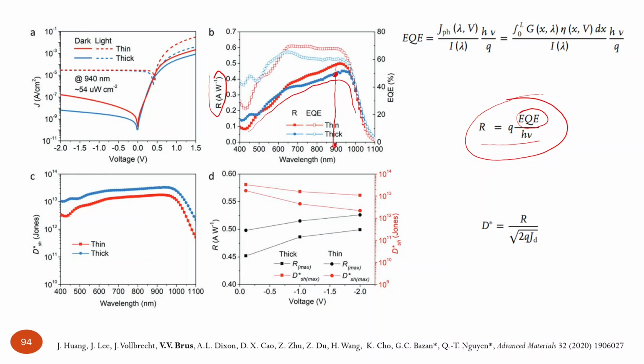So that is used for calibration of photodiodes, and once you have such a spectral distribution of this responsivity and some unknown monochromatic light source, like some laser, you can shine this laser on the photodiode. You know the wavelength, you check what the responsivity will be, and you measure the photocurrent, which is experimentally measured. So you check responsivity for this photodiode at the given wavelength, and that's how you can easily determine the power of this monochromatic light beam. So that is the main purpose for calibration of signals.